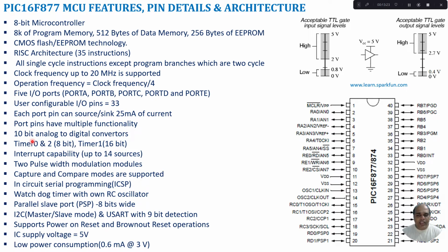So this interval can be varied, and this timing can be used for generating an interrupt. This interrupt can be used for toggling an LED and for sending information. We can make use of these timing signals. So these are the hardware timers. I have 3 in number: 2 8-bit timers, timer 0 and timer 2, which means each has a register of 8 bits. And timer 1 is a 16-bit timer. It has a register of 16 bits.